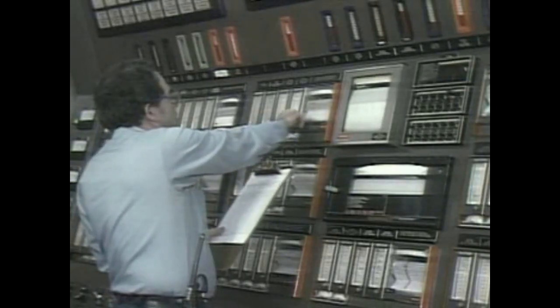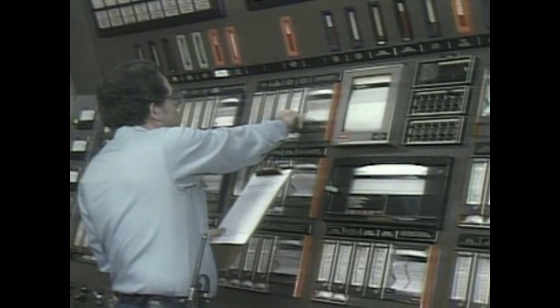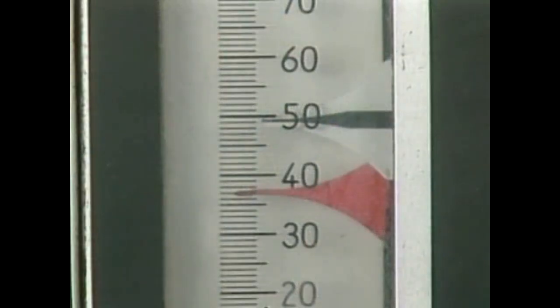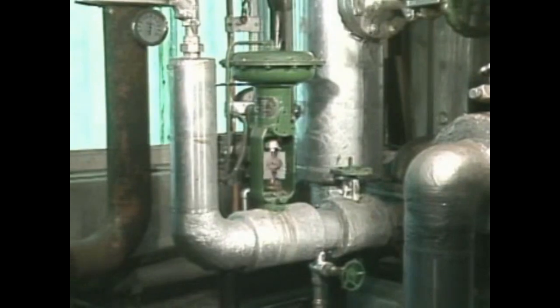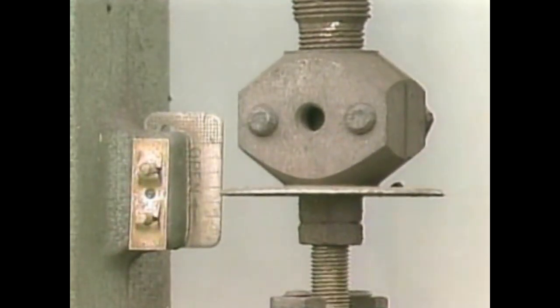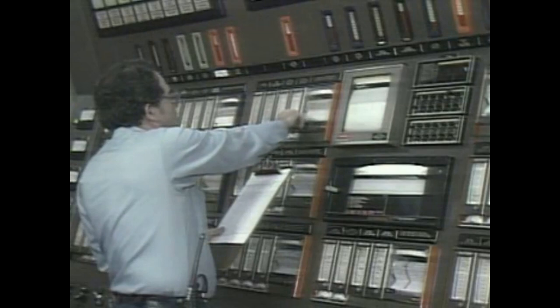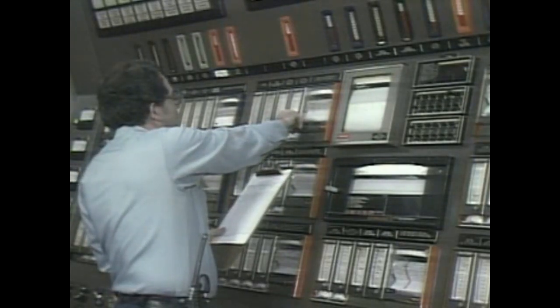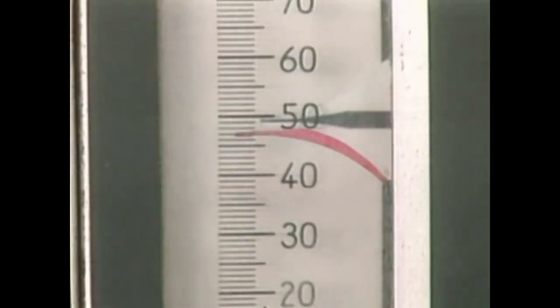The way the feed rate is kept within the specified range depends on the system. In this system, a flow controller compares the rate of flow in the feed line to a preset value. If the feed rate needs to be adjusted, the controller signals a control valve to open or close. A distillation system functions most efficiently when its feed rate is kept within an established range. When the feed rate is regulated by a flow controller, slight variations in the rate can be expected. However, large variations can greatly affect a column's performance.